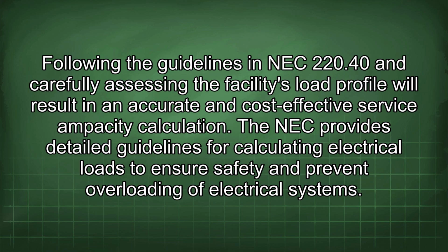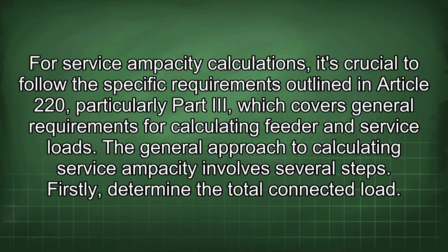service ampacity calculation. The NEC provides detailed guidelines for calculating electrical loads to ensure safety and prevent overloading of electrical systems. For service ampacity calculations, it's crucial to follow the specific requirements outlined in Article 220, particularly Part III, which covers general requirements for calculating feeder and service loads.